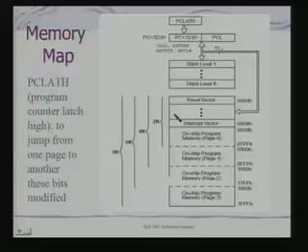Interrupt vectors are what? If an interrupt occurs, where the jump has to take place. So the first page is typically allocated for those purposes, and then subsequent pages are for on-chip program memory. Okay? So your program is typically stored in this area. And what is interesting is that this first part is separated out.